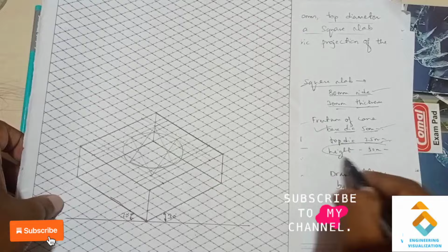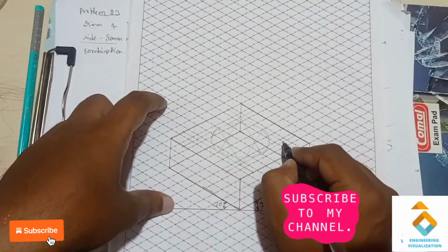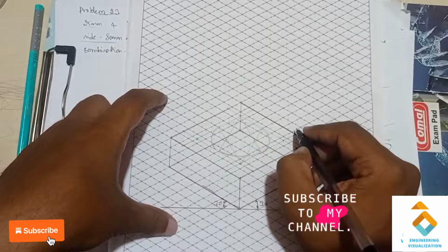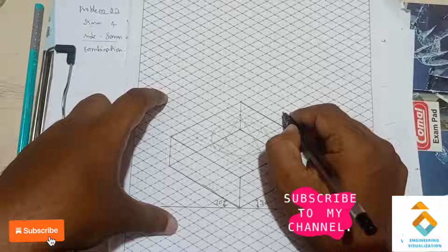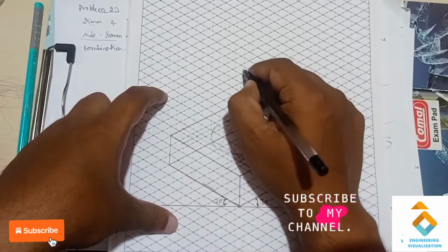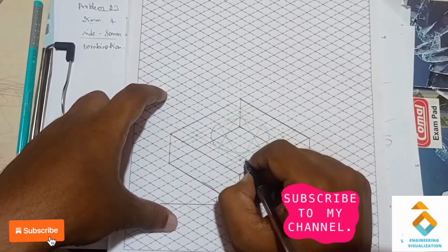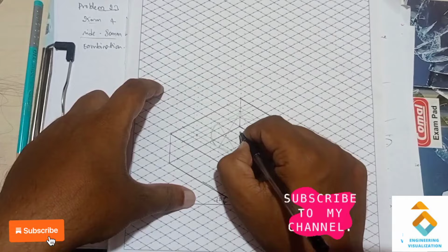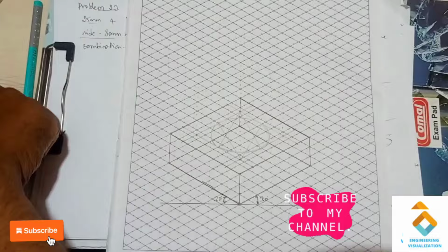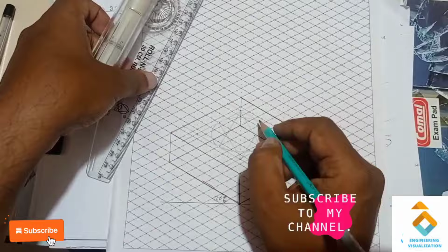Now we have completed the base diameter 50, that is we have drawn an ellipse here. Now by taking 50 mm the inside box, we have to consider the height. The height is 50, so count the boxes. The count comes from exactly the center of it. So count 5 boxes, and again here we need to construct another box of 50. From there we will again subtract, so that we will get another box of 25. Now I will draw another box of 50 by 50 at a height of 50 mm.